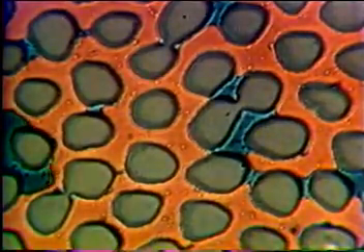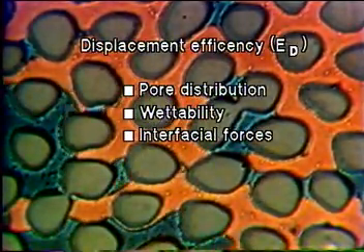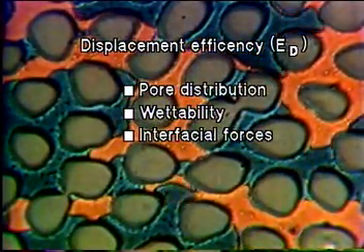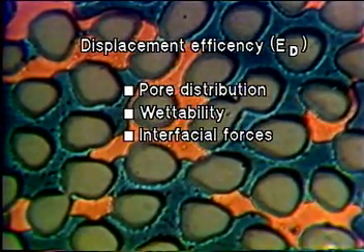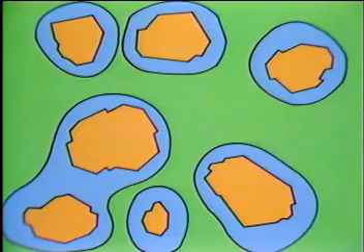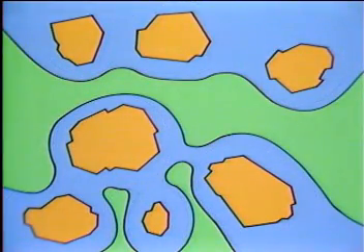Oil is not displaced in a piston-like manner. As fluids move within a porous medium, the displacement efficiency is determined by the size and nature of the pores, the rock wettability, and the interfacial forces that exist between the fluid phases. Here, for example, we see a representation of what occurs as water displaces oil in a reservoir. Some of the oil is displaced early in the drive. A little later, even more has been pushed ahead, but we also begin to see that because of capillary forces,